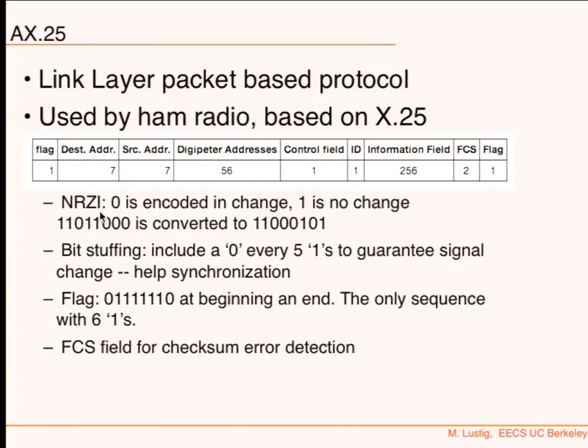That means that a bit with value 0 is encoded in a change of bits. It's kind of like a Manchester coding. Remember that we talked about this? So it's encoded in a change, from low to high, from one frequency to another, or from the high frequency to the low frequency, and that means that bit 0 is being transmitted.